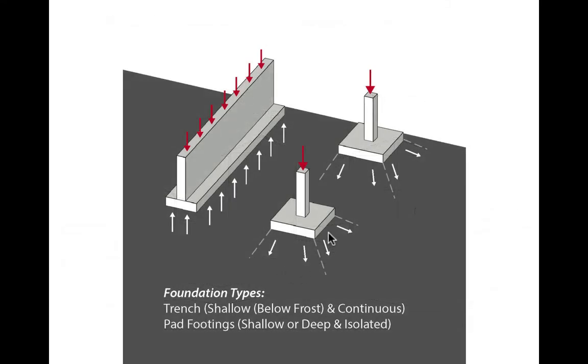We talked about the way that these spread footings distribute their load. That's very analogous to the way that slabs collect loads. And so what we're worried about is both transforming, in this case, the exact opposite, taking the point load of the column, spreading it out over a safe area. But we're also worried, just as we are in slabs, about punching shear and the need to provide often a shear panel or something that increases the intersection between the surface of the column and the section of the footing.